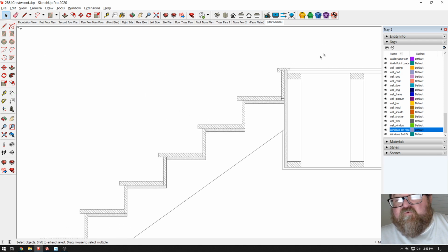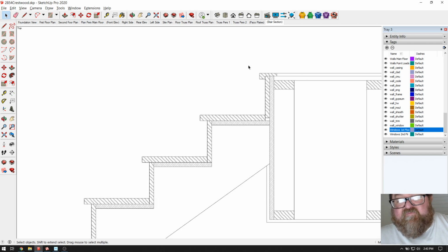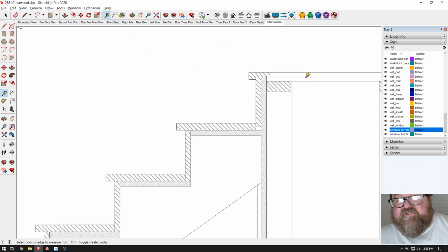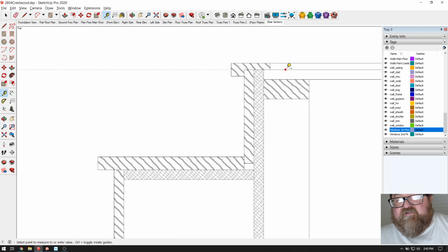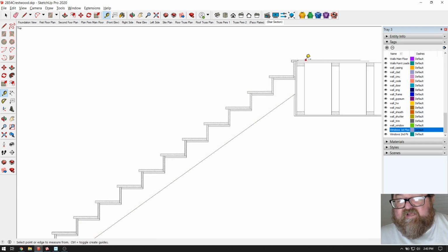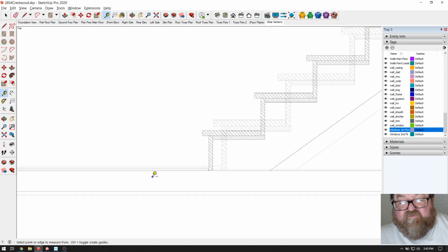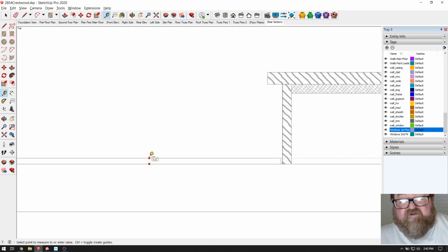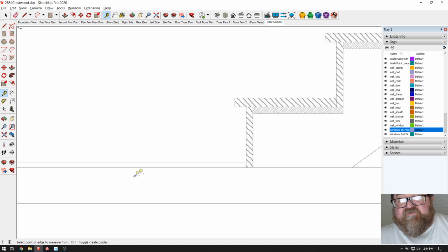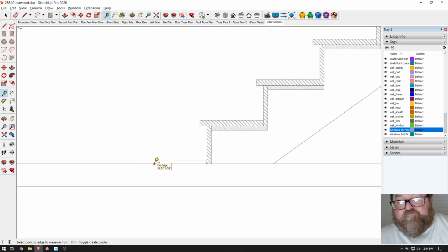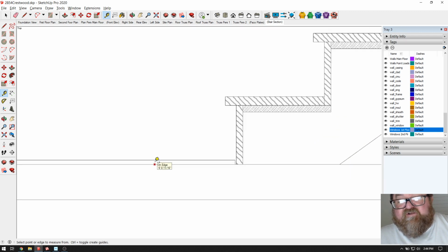And the most important thing is if you're the homeowner, you have to commit to the finished floor thickness, okay? And in our case, it's 1/2 inch engineered flooring. It's this 1/2 inch right here. And you need to know that, and you need to know what the top to the bottom floor covering is going to be. And in our case, it's the same. It's 1/2 inch. This is going to be a floating floor down here on a pad, which total thickness about 1/2 inch. Do not start building your stairs without knowing what your finished floors are going to be.